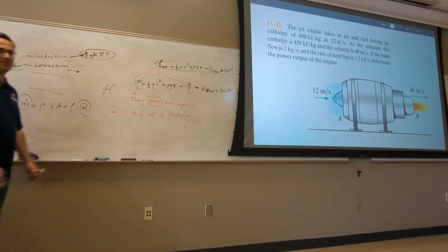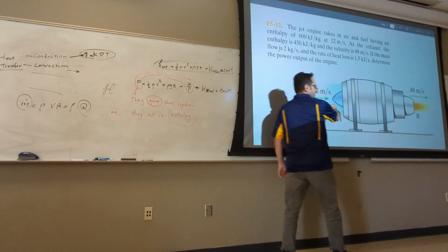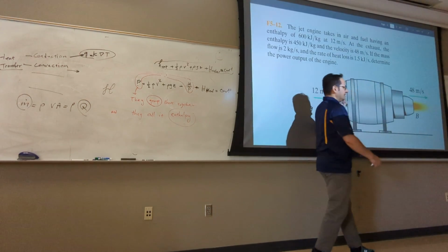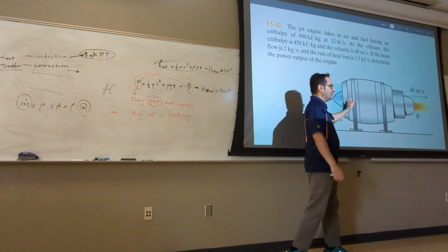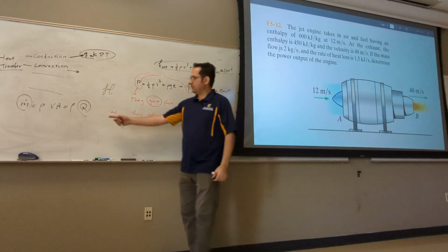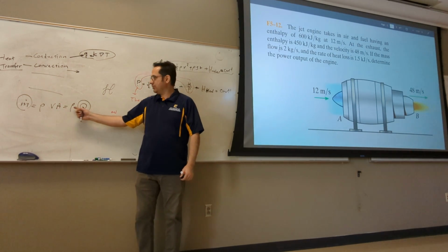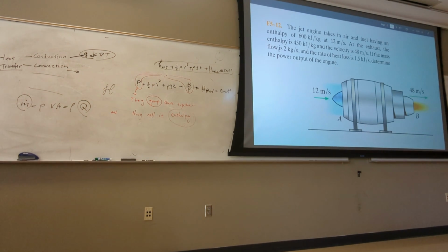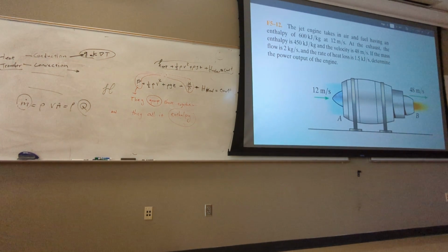That means the density of air in the inlet is different from the density of air in the outlet. In fact, density is variable in many places all along it. So in the compressible, not only do you want to see Q, which is VA, but also you want to know information about density. So that's the reason you say m dot. But look, since you have all this in the formula, substitution doesn't matter as long as you know what the m dot is. It's rho times Q. So you already know how to work with Q. Substitution is going to be very straight. So also heat loss, Q dot, it gives you heat loss, which is 1.5 kJ per second.